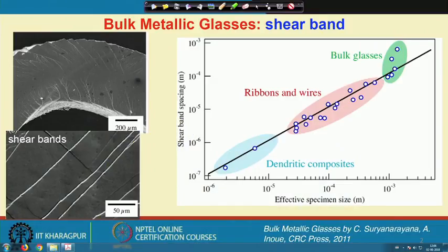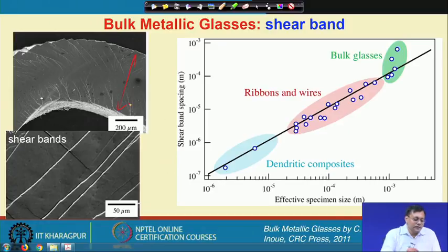The microstructure of a thin plate is shown here, which was bent on an anvil, and you can see how the shear offsets have occurred near the surfaces. Individual slip or shear steps involve some amount of strain.